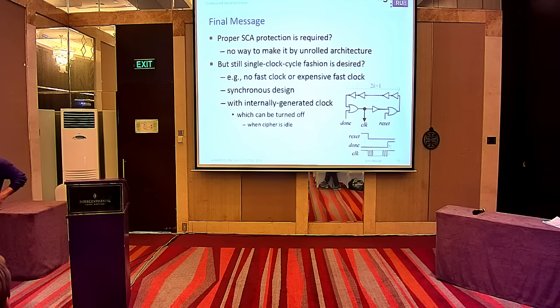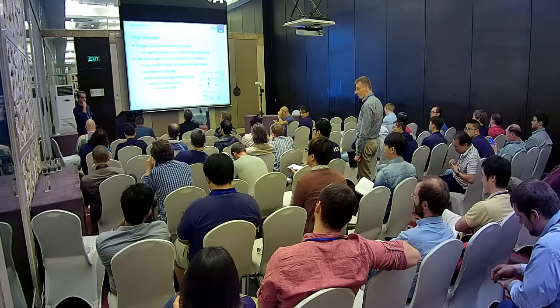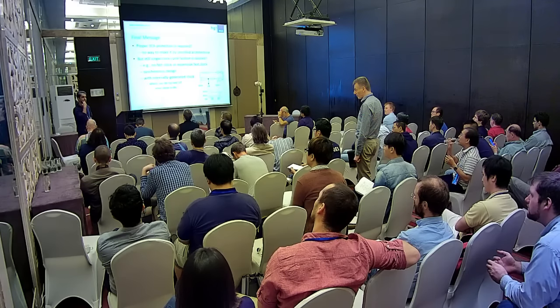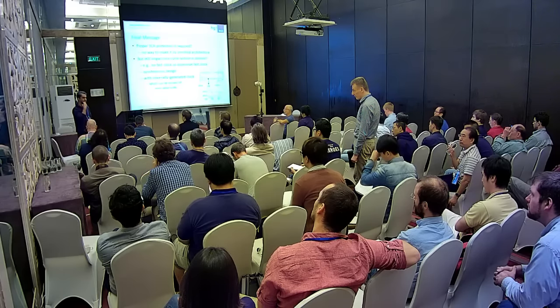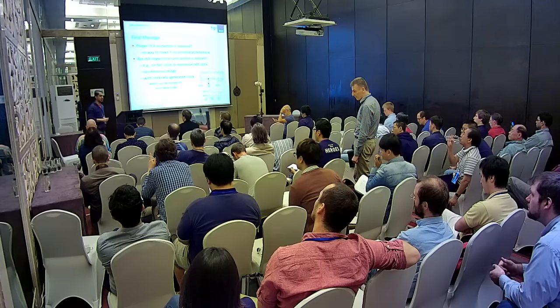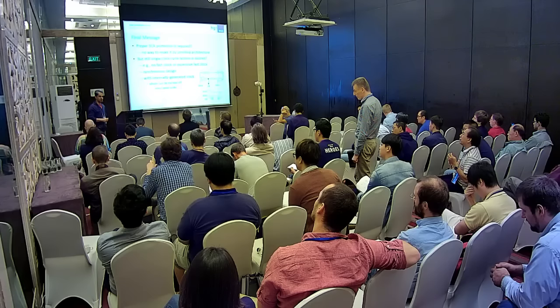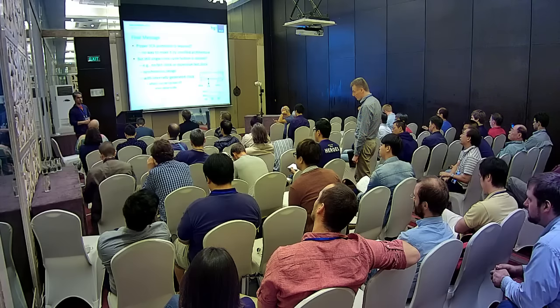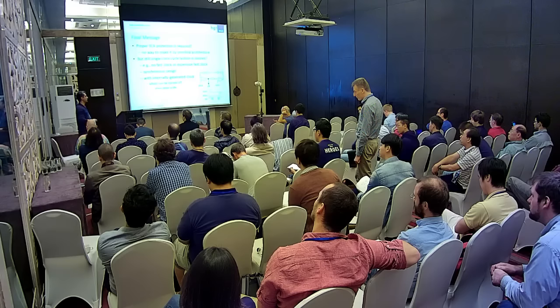A design like Prince is specifically optimized to be implemented very efficiently, with a very low latency, assuming that you need to be able to execute the entire block cipher call inside one clock cycle. Fully unrolled. And if this restriction is not really there anymore because we have a fast internal clock anyway, then maybe we're not really going towards designs like Prince, but other designs could be very suitable as well.